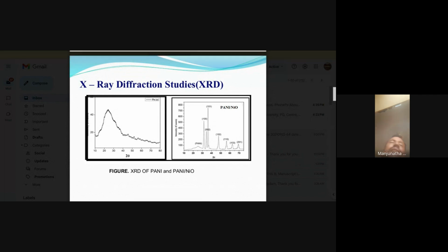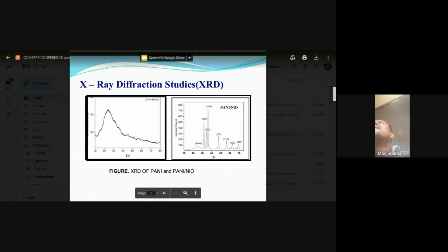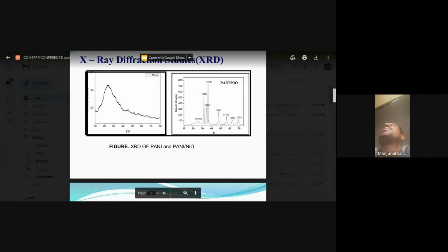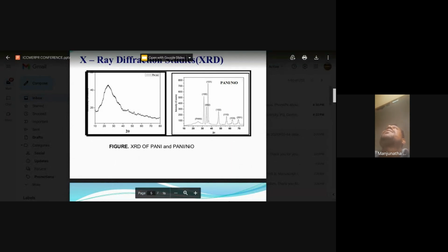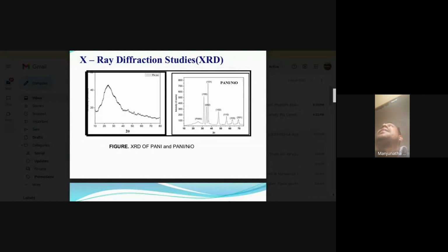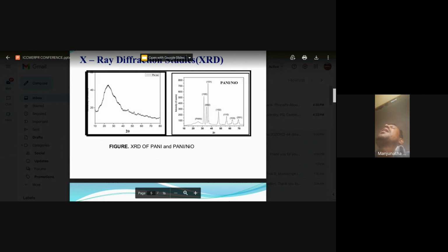using the Debye-Scherrer formula, we can find out the crystalline grain size, and H, K, L are the Miller index values and crystal planes. So the first one is a broad peak. You obtain the broad peaks, that's why it's easy to tell. This is the amorphous nature, and this is the crystalline nature. Only these two parameters bifurcation, and then the third parameter is how to find out the crystalline grain size,